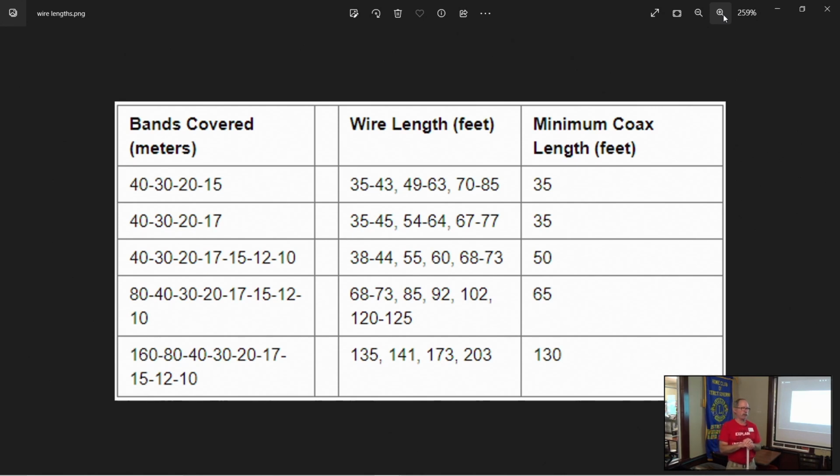If there was a problem, I'd use an RF choke. In addition to the 9-to-1 balun, I'd use a 1-to-1 choke after that on the coax to keep RF off the coax. If you're not using any kind of counterpoise, it will use your coax shield as a counterpoise.